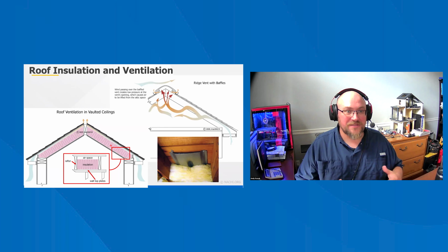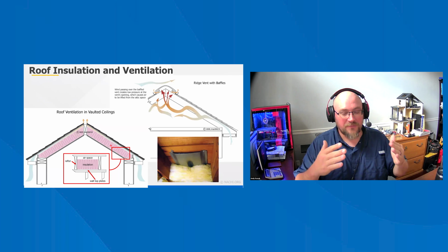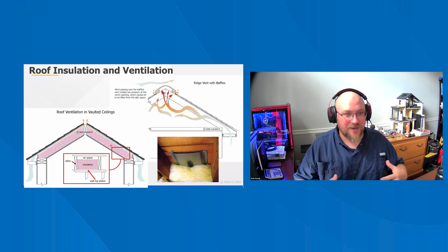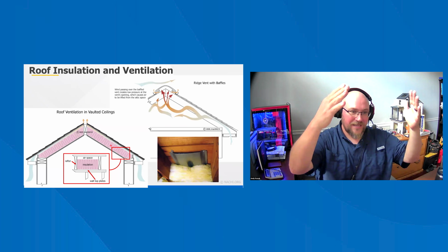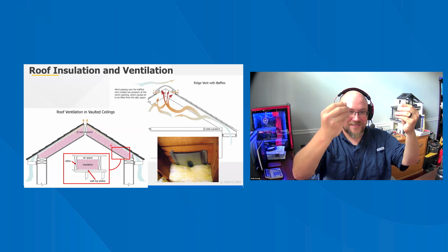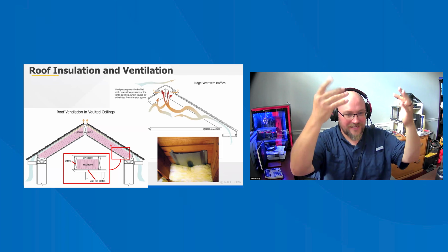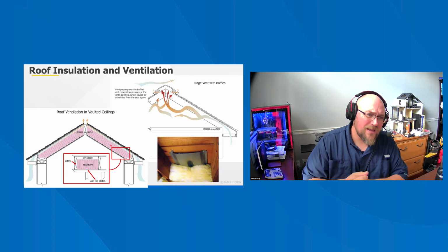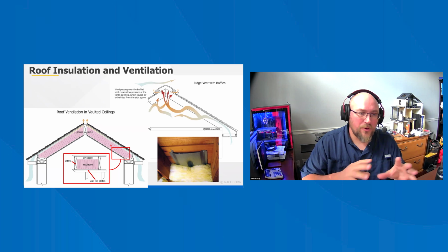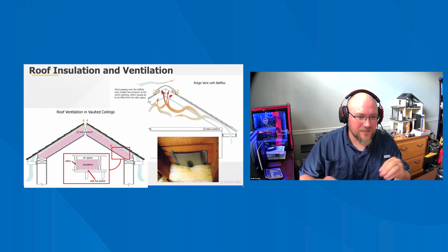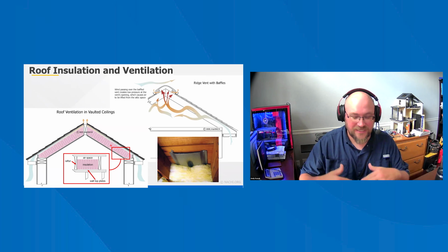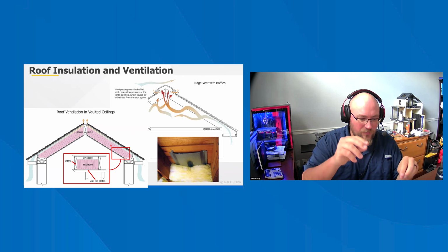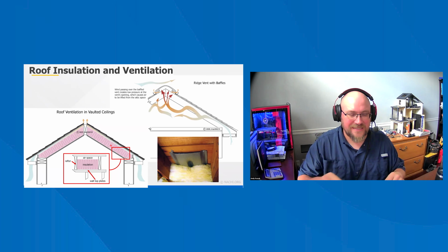So now you're running into the possibility of the bottom of that insulation being the dew point location. That hot, humid air being pumped in from the bathroom collects on the spray foam, and once there is so much moisture there, it starts to basically rain inside that attic. There was evidence of moisture drips, because there's no insulation on the ceiling, only on the roof decking, so we were able to see where moisture had dripped onto the ceiling framing.